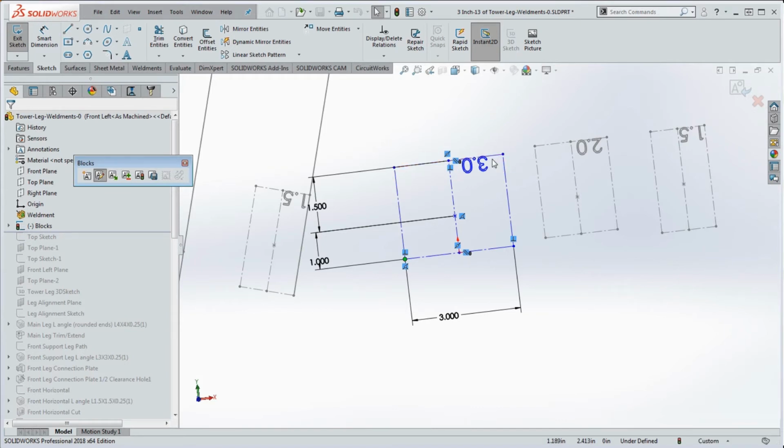So every structural member you put in there that's not axially symmetric, you need to be able to align that to something. Otherwise, that structural member is going to spin on you. And you need to be able to get that nailed down. So the nice thing about this approach here, when you're putting in non-axially symmetric structural members, is that you have the capacity to have an element that's in that sketch that drives the pass segment line. You have an element in there that you could use to align it, instead of having to rely on geometry that's on the outside of that sketch. So that's very convenient having that.